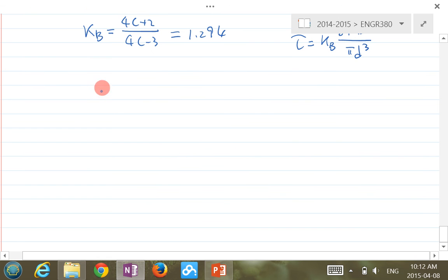So we need to know what the NA is. NT is a given, 40. And the spring is square and ground ended. So which means what? NA equals NT minus 2 from table 10-1. So which is 38.